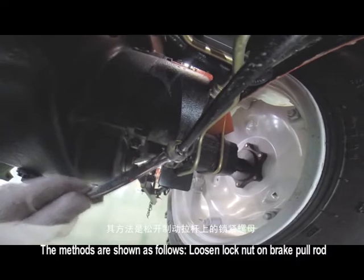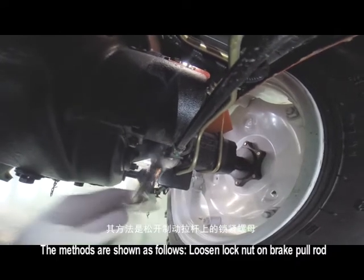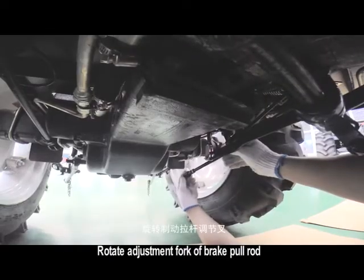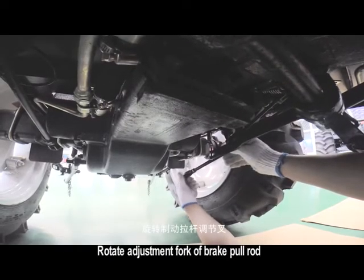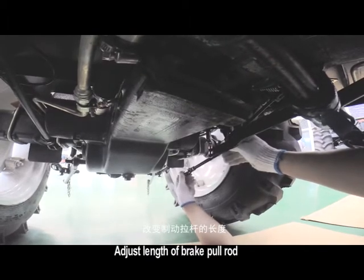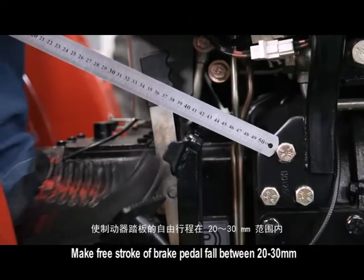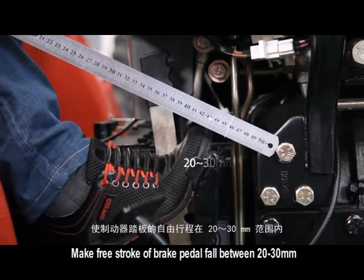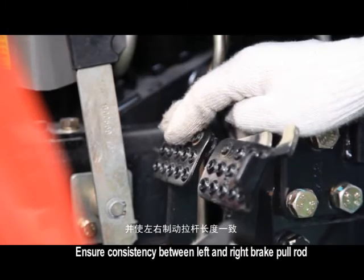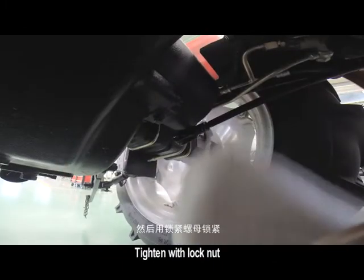Free stroke adjustment of brake pedal. The methods are shown as follows. Loosen lock nut on brake pull rod. Rotate adjustment fork of brake pull rod. Adjust length of brake pull rod. Make free stroke of brake pedal fall between 20 to 30 mm. Ensure consistency between left and right brake pull rod. Tighten with lock nut.